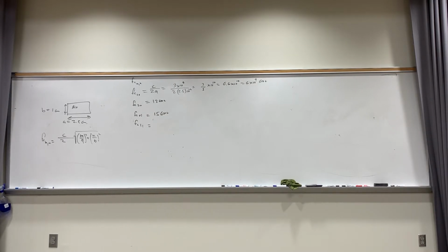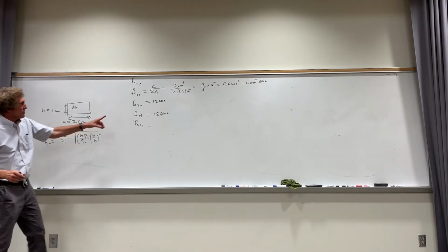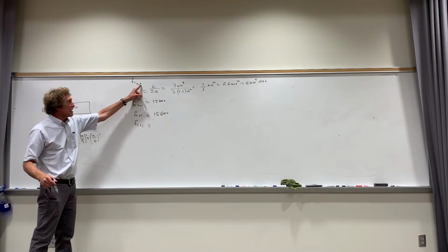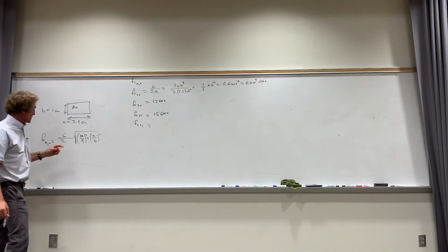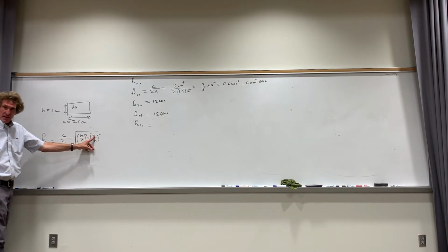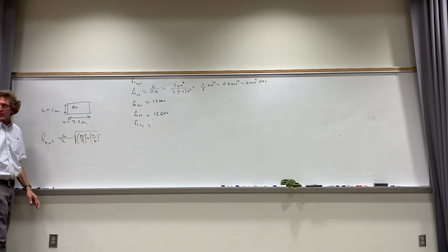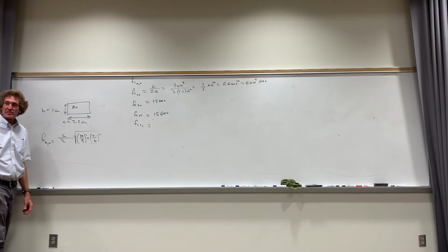Can you explain how you get the 1 again? Yeah, all the M and N are associated with the mode numbers. Like I have F, C, M, comma, N. So for a 1-0 mode, M would be 1, N would be 0. That's the only thing I'm trying to show you. Got me on this, guys? Yeah, that makes a lot of sense. I'm sorry if I didn't say that clearly.